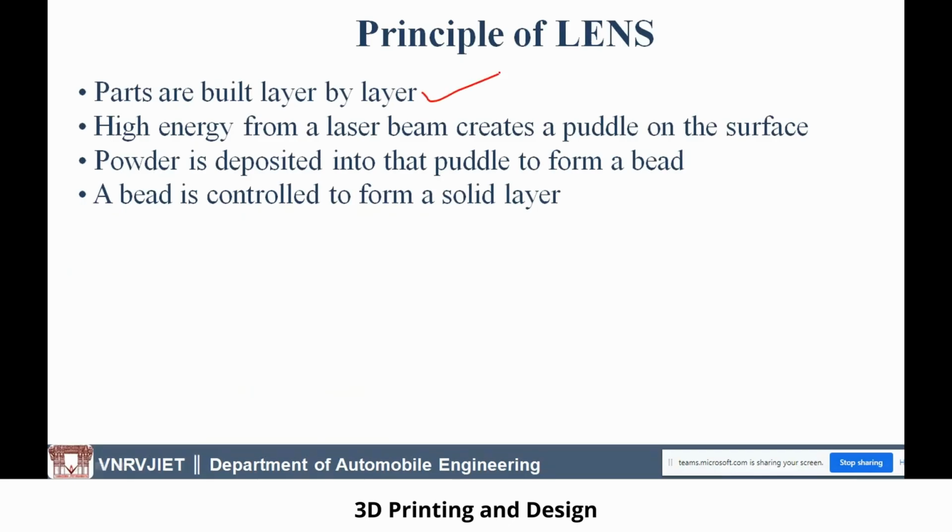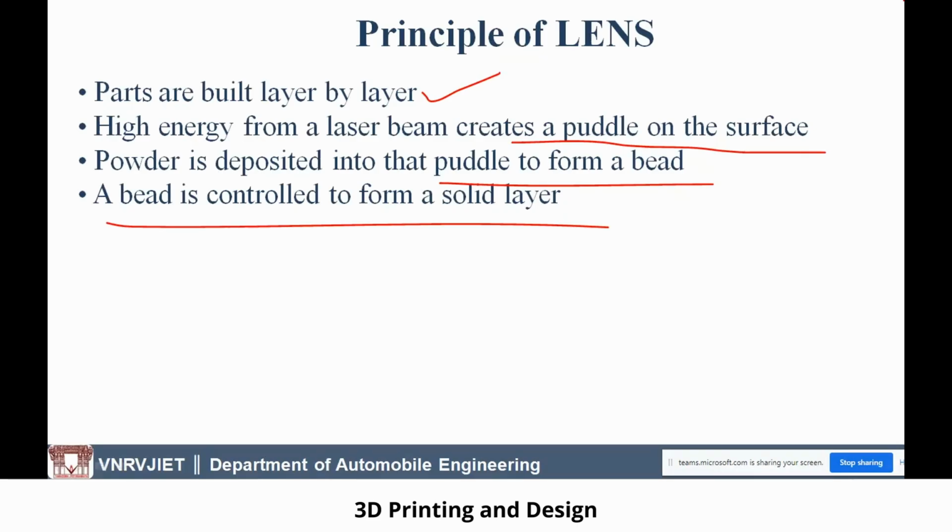but some of the important things are, it is also a laser-based process, and high energy from the laser beam creates a puddle on the surface. That puddle means a liquid form, and the powder is deposited onto the puddle to form a bead, and the bead is controlled to form a solid layer.